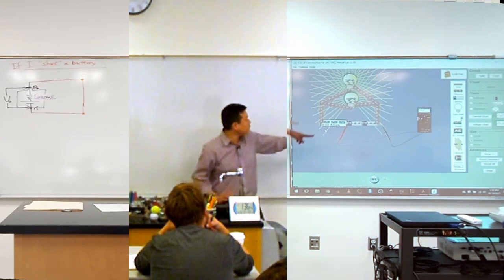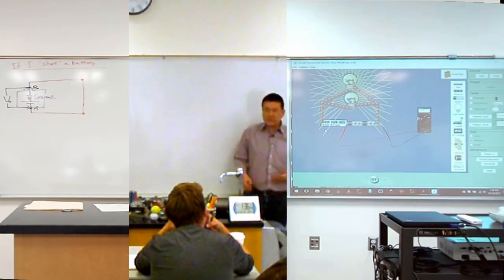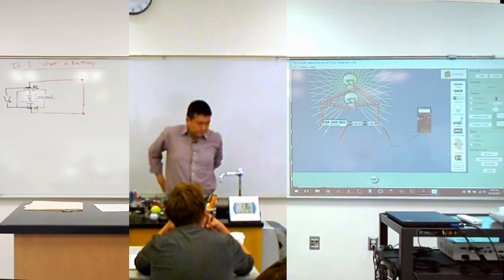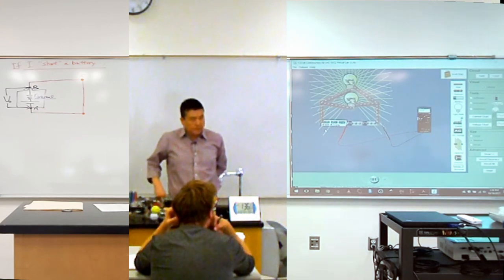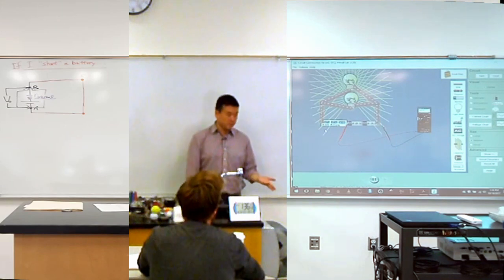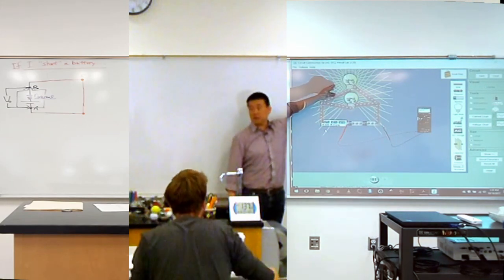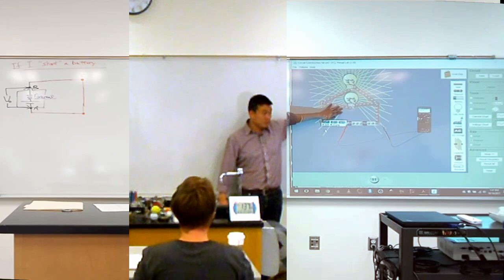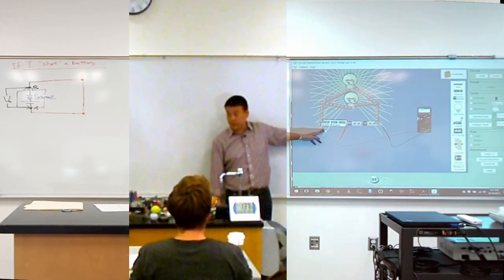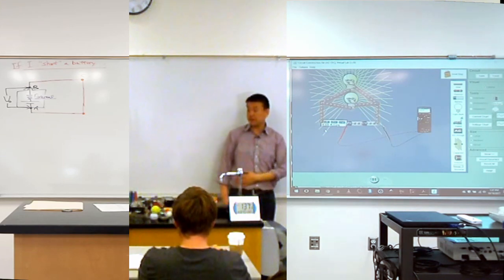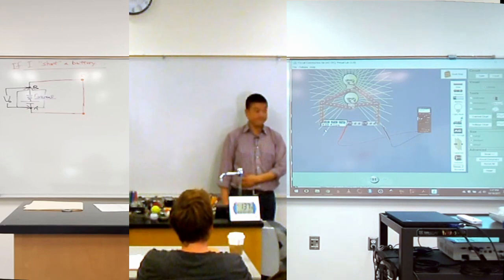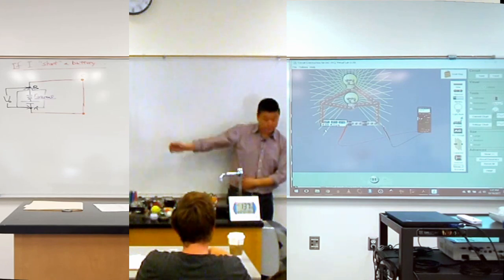So Kevin, when you connect more light bulbs in parallel, what's the effect of doing that, in terms of, let's say, resistance of the circuit? When you add more light bulbs in parallel, what does that do to the resistance? Lower. You could say that's why there's more current here, according to Ohm's law. Okay, what's the lowest resistance can be? 0, right? How would you build a circuit with a 0 resistance? Just with the wires, right? That circuit. So let me do that.